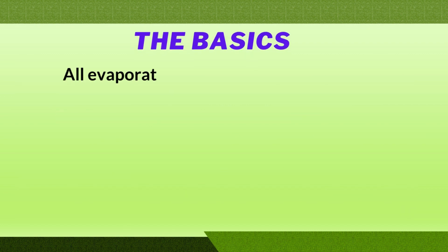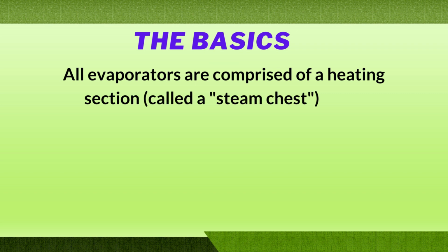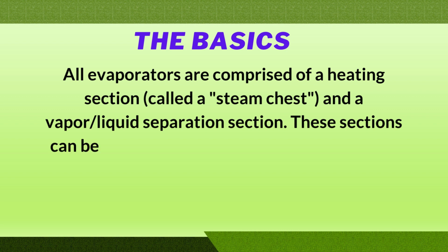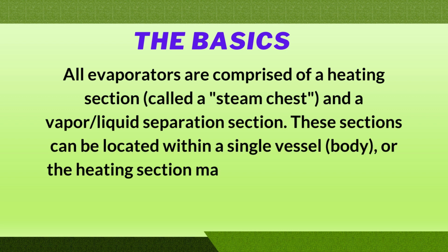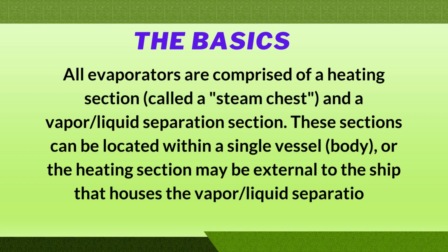The basics. All evaporators are comprised of a heating section, called a steam chest, and a vapor-liquid separation section. These sections can be located within a single vessel, or body, or the heating section may be external to the vessel that houses the vapor-liquid separation section.